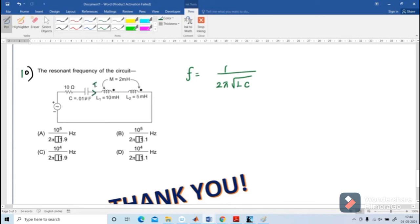In the first winding the current is leaving the dot, and in the second winding also the current is leaving the dot. What is the equivalent inductance? L1 plus L2 plus 2 into M. What is it? 10 plus 5 plus 4. The value is 19 millihenry.